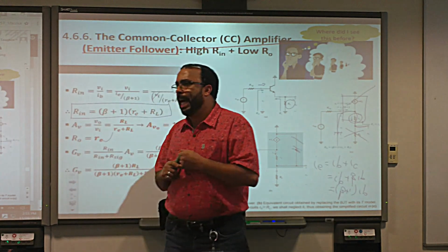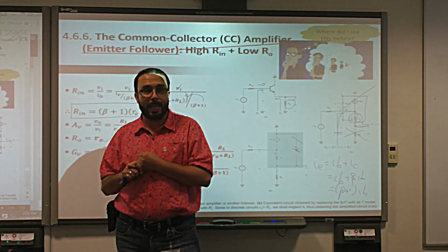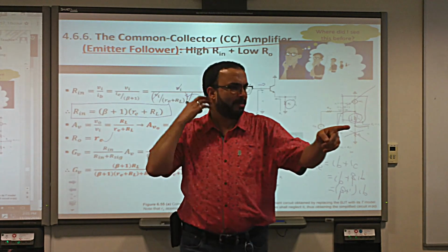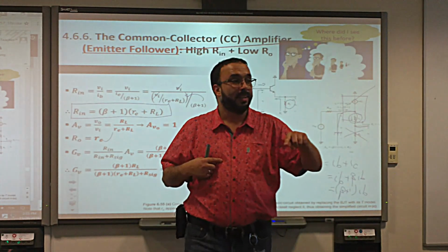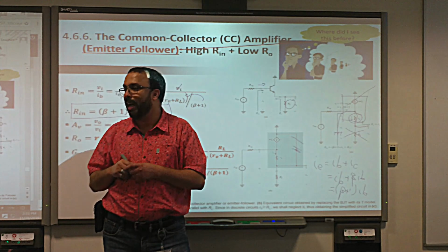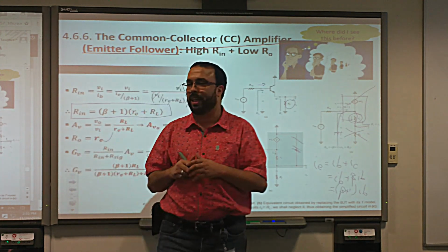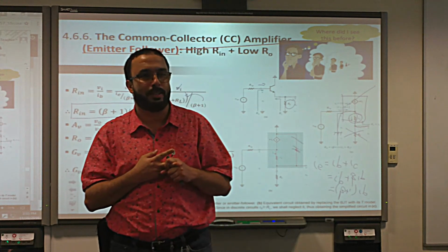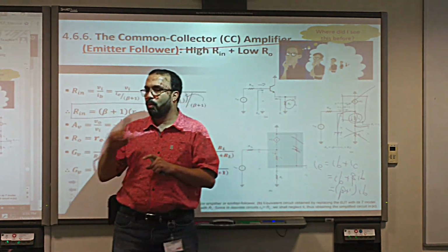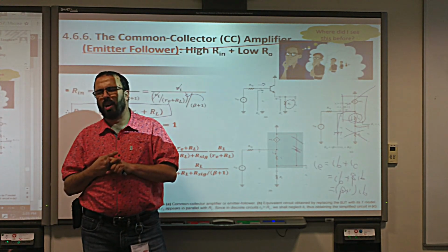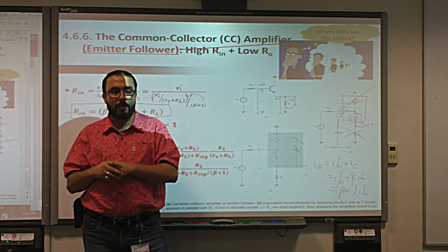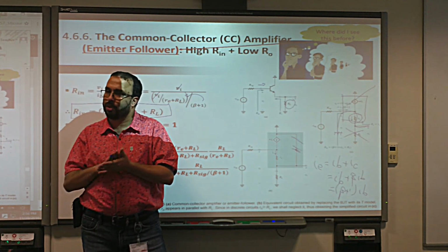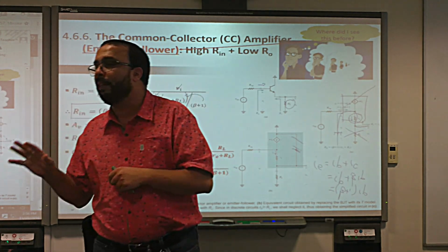Voltage buffers have three major characteristics. Number one, the open circuit voltage gain is equal to 1, or unity gain. This is number one, because they don't amplify the voltage, they keep the same voltage, yes? Number two, the input resistance is very high, extremely high. And number three, the output resistance has to be very low. So three things: input resistance high, output resistance low, and the open circuit voltage gain unity, 1. When you say unity gain, it means 1. We are talking about the open circuit voltage gain in this case. Three things, remember that? Very important. I can ask a question anytime. We explained why. You can go to the video and check that. We're not going to waste our time there. So we need to have these things in here.